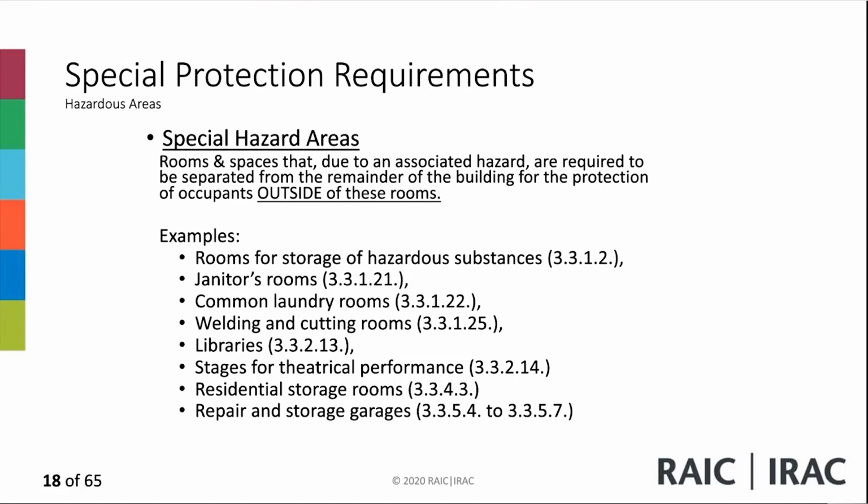Except as provided in sections 3.3.5 and 3.3.6. Those are related to industrial occupancies and design of hazardous areas. But in the general section, except as provided in 3.3.5 and 3.3.6, the storage, handling, and use of hazardous substances shall be in conformance with provincial or territorial regulations or municipal bylaws.